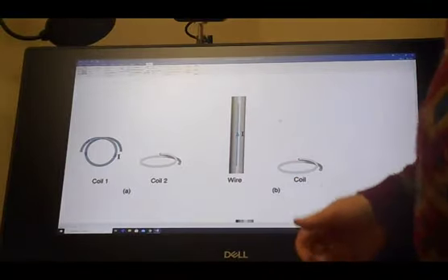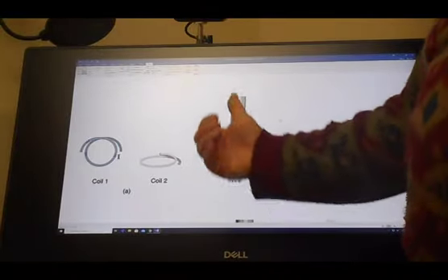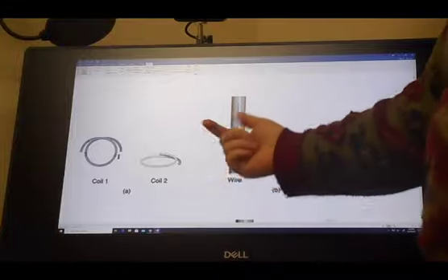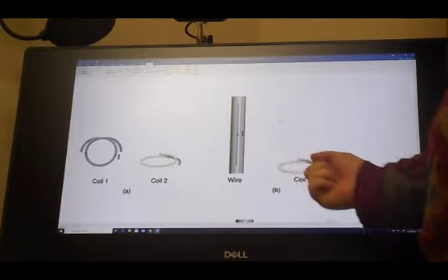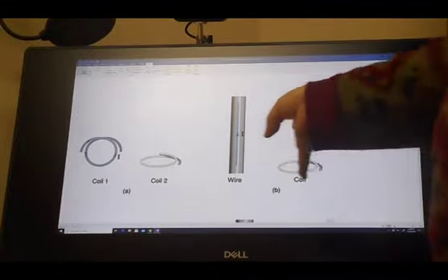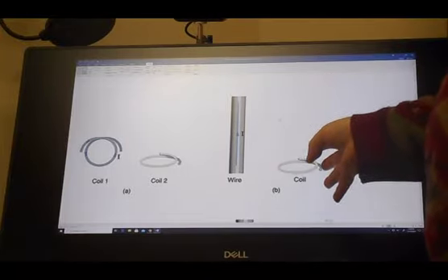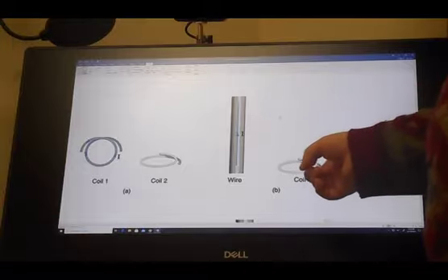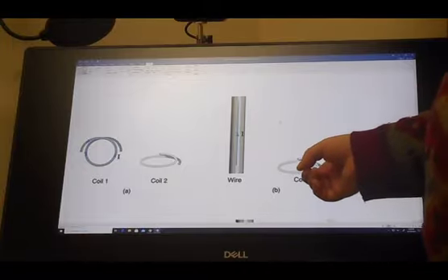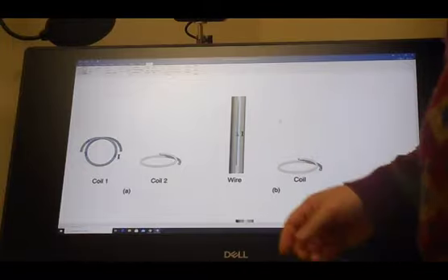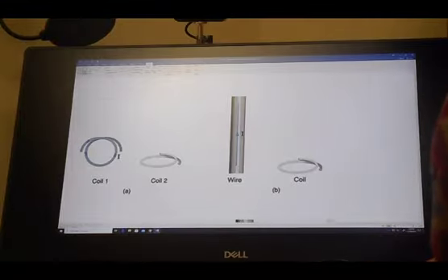Okay, the other wire here, current, magnetic field again actually bypasses this coil here, so it goes like this, and no matter if it's increasing or decreasing or what have you, it doesn't change anything, you don't get anything in here. Again, you have that cosine of 90 degrees, which comes out to 0. Okay, next diagram.